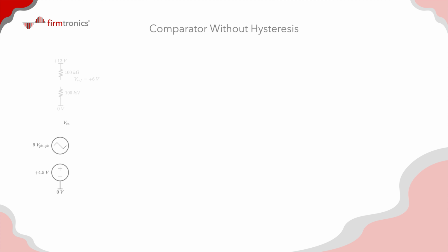The typical comparator configuration looks like the following. A reference voltage is chosen to compare the input signal against. The reference voltage is generally made up by creating a simple resistive divider. However, if precision is required, it is better to use a Zener diode reference as it has better voltage stability and temperature performance. The choice between connecting the reference to the non-inverting or inverting terminal depends on the output polarity required by the design.